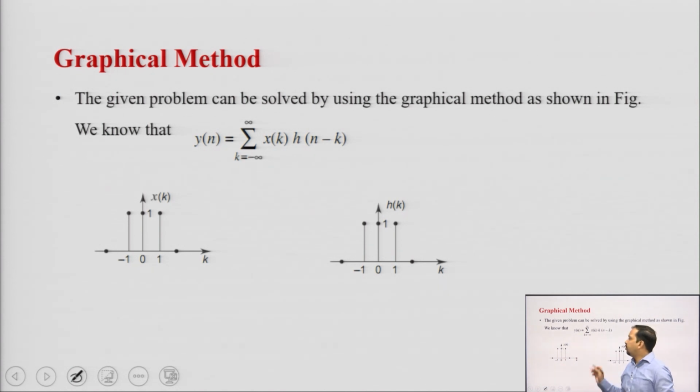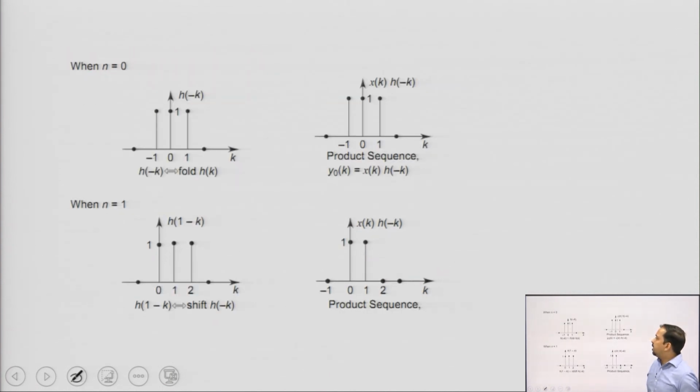First of all, we are going to draw x[k] and h[k]. Now, instead of h[k], we are putting h[-k]. How do we get h[-k]? We just perform the mirror image about the vertical axis. Since the signal is symmetric, it will not affect it; the signal will remain the same because it is also an even signal. After that, we will multiply h[-k] by x[k].